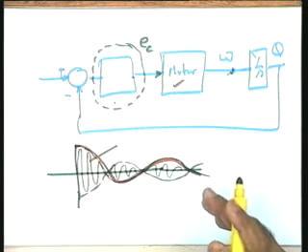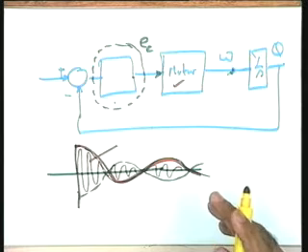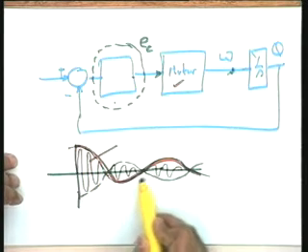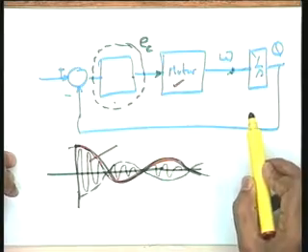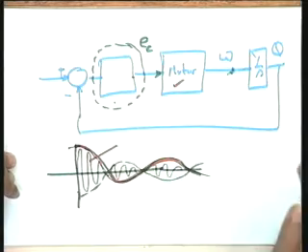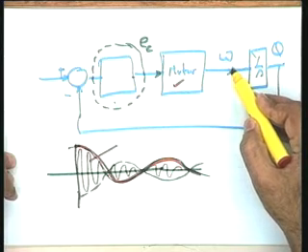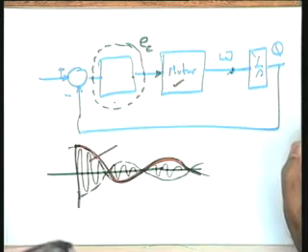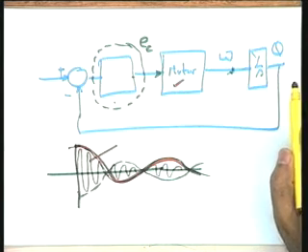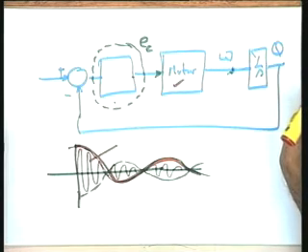And as far as the system is concerned, the control information is carried in this envelope, and therefore the mathematical model of the system could be taken as the relationship between the speed or the position as the output signal and the envelope of this signal as the input signal. So my point is this, that if the signal coming to the AC motor is directly a low frequency signal through a modulator, that low frequency signal will be taken as the input for the motor.